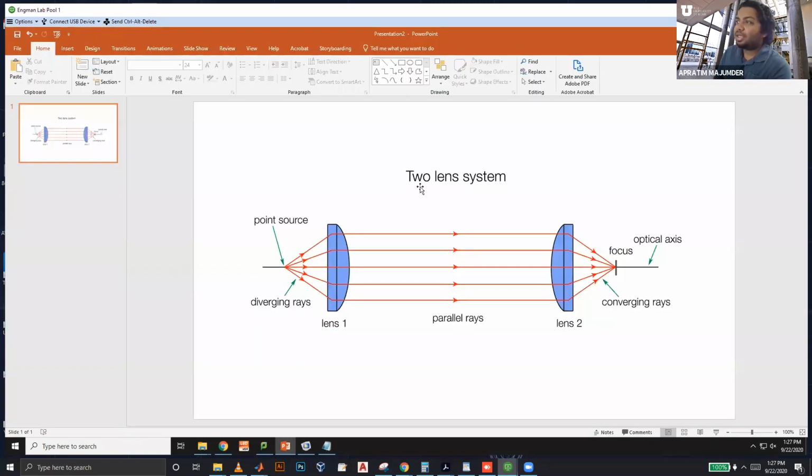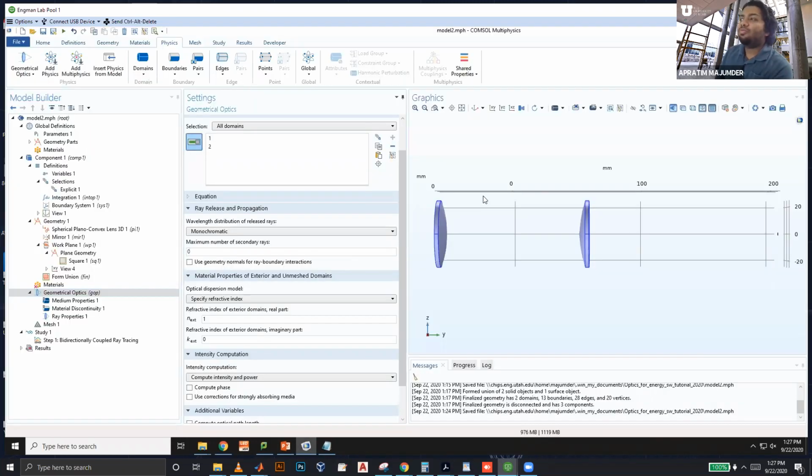If the system has certain reflections or scattering, it creates secondary rays. But in this case, we are setting those to 0, which is a special case to reduce computation time for now, because we are not worried about those rays: none of the surfaces will have any extra scattering or reflection. So set that to 0.